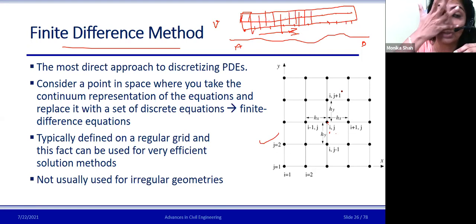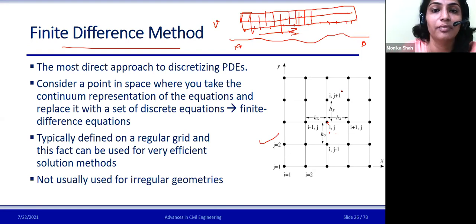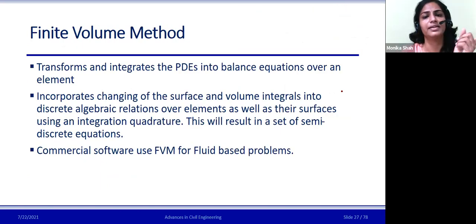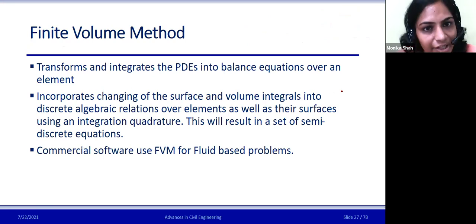Generally, the solution of this partial differential equation is expanded using Taylor series expansions. But as I have said, it is used for regular geometries. When I have something like a screw, or a curvature on the bodies, in such cases it is a big no for the finite difference method. Such things can be handled by the finite volume method.